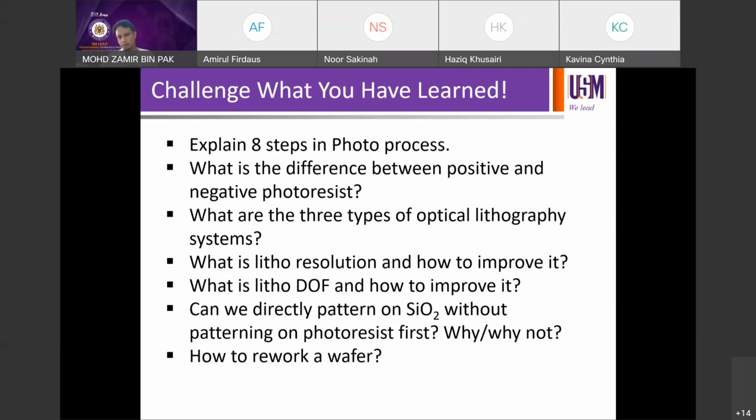After the photoresist, we align and expose. Not yet, we bake first, soft bake. Soft bake, and then align and expose. Then there is another bake. What is it called, the second bake? Post exposure bake, PEB.